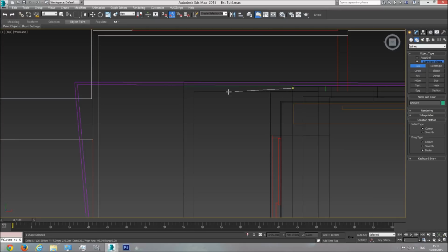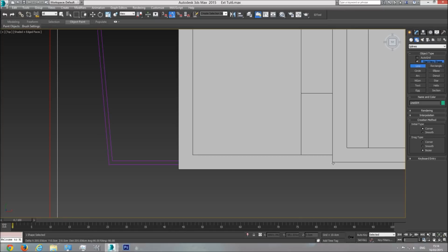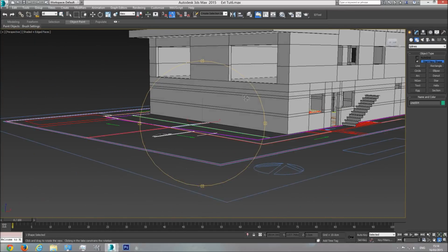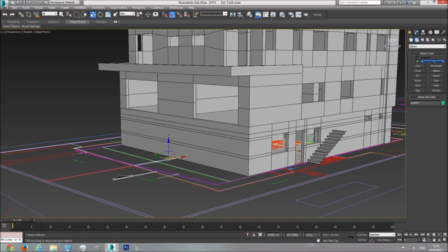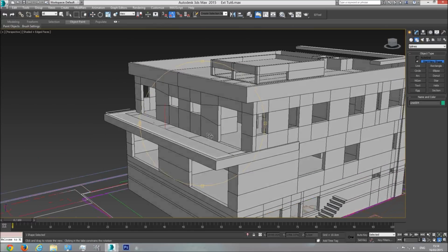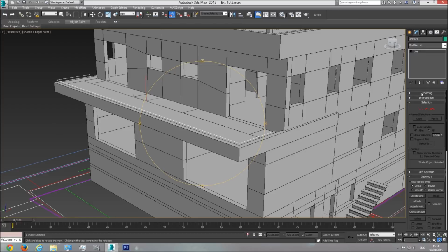I'm going to create one. When I hold shift, the line goes in a straight line. So I'm going to go here, continue here, and F3, finalize the line here. To finalize the line, I clicked the right mouse button. Now I'm going to take my line up here, and I'm going to give it a height of 90 centimeters and a thickness.